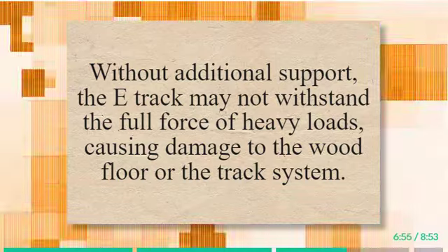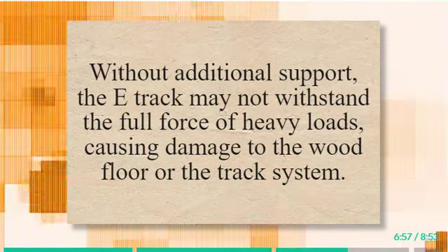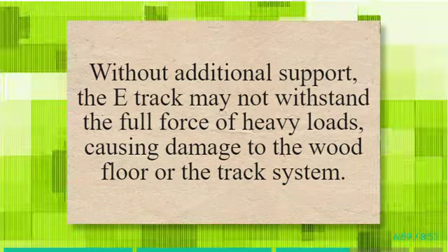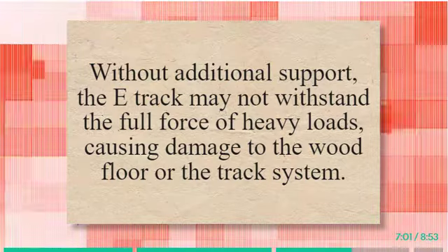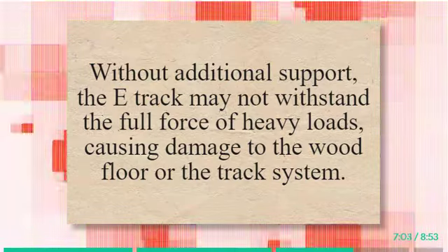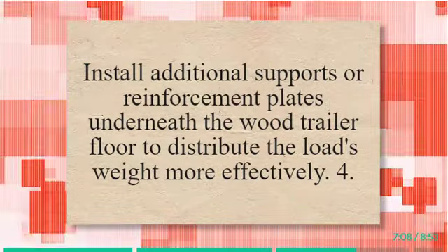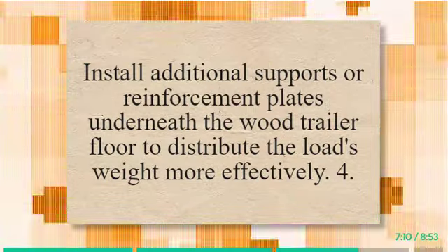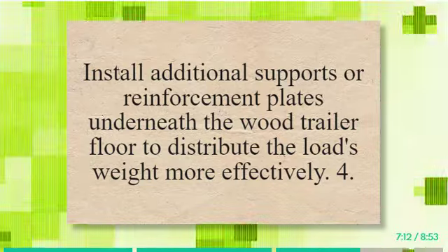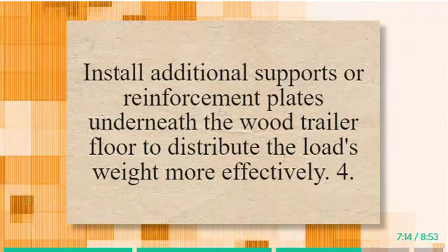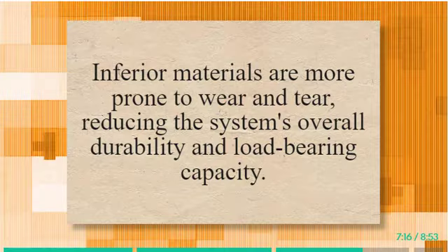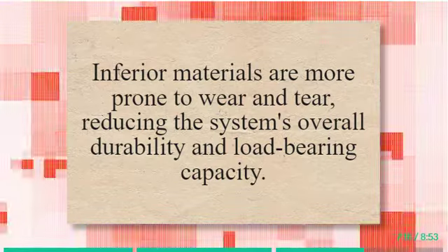3. Overlooking trailer frame reinforcement. Neglecting to reinforce the trailer frame can be a serious oversight. Without additional support, the E-Track may not withstand the full force of heavy loads, causing damage to the wood floor or the track system. Install additional supports or reinforcement plates underneath the wood trailer floor to distribute the load's weight more effectively.